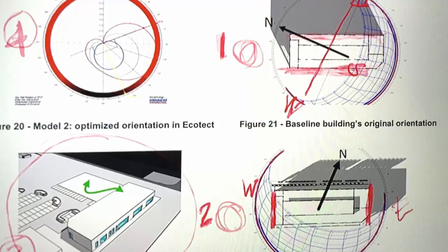to sun even in the summertime, where you don't really need the sun for heating purposes, probably for natural daylight, that's okay. But the east and the west will cause a lot of heat gains that will mean you have to activate your mechanical cooling system in order to minimize the impact of the heat gains. So again, number 2 is the preferred solution in that case.